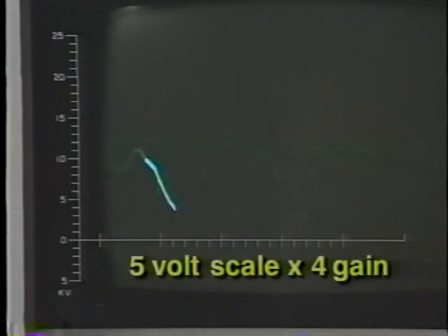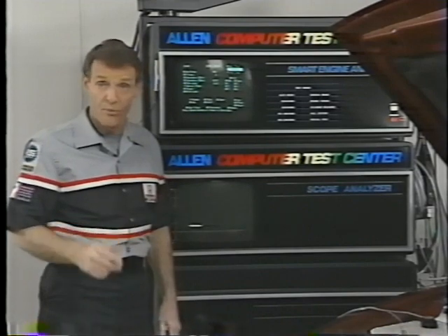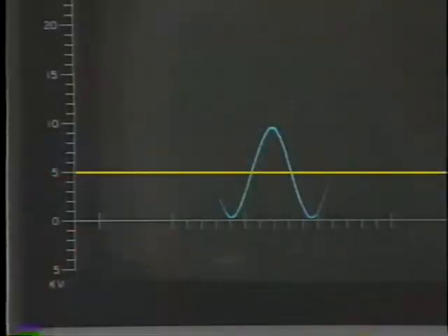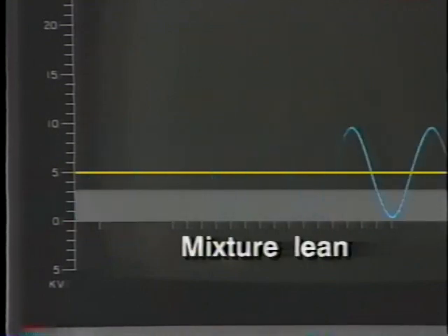Once the element reaches operating temperature, the output from the oxygen sensor changes from high to low very quickly, many times per second. Keep in mind that the oxygen sensor senses only the oxygen in the exhaust stream, not unburned fuel. The controller, however, interprets that signal as mixture-rich or mixture-lean and responds with an adjustment in how much fuel it delivers.